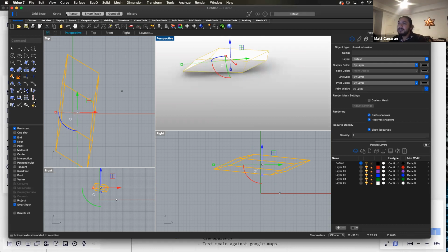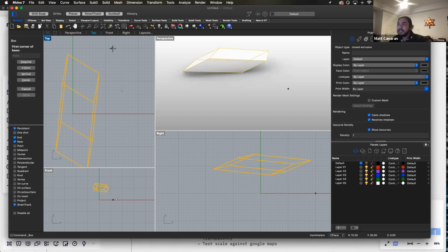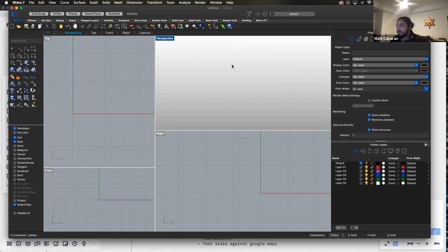So we've talked about Gumball. The only other ones that I'd say you should use on a regular basis, or I use on a regular basis, are Grid Snap and Ortho. And we talked about those two, right? Like Grid Snap, if I turn Grid Snap on and I draw an object, I snap exactly to the grids that are on the screen, and then with Ortho, I can only draw lines along 90 degree, 180 degree, 270 degree, right angles basically. Okay, great.